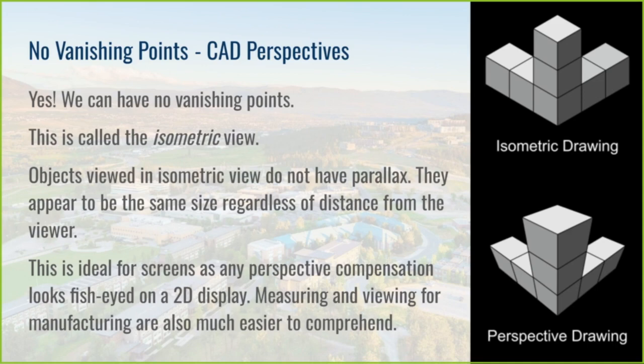If you're in perspective, you can see that the lines aren't perfectly parallel to each other. We know that they are, because mentally that's how we've seen the world for a long time, but we know that there's at least a vanishing point that goes down. It looks like there's probably a vanishing point over here and one over here. So that's 3 vanishing points. If we rotate that, those angles shift as we move that part, and it's difficult to say what is parallel, what's not, what if it's on a slight angle. Whereas in an isometric view of things, there's no room for error in that regard. It's going to be perfectly parallel, perfectly perpendicular.